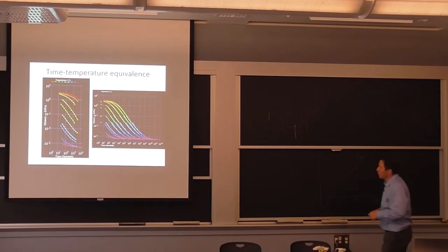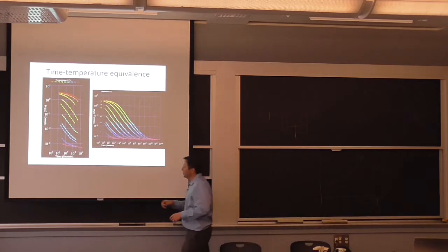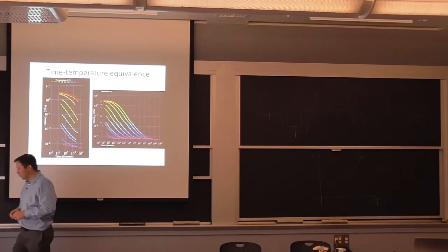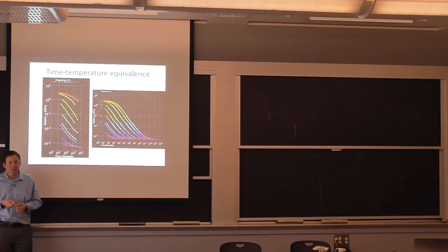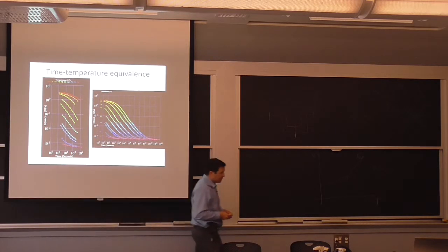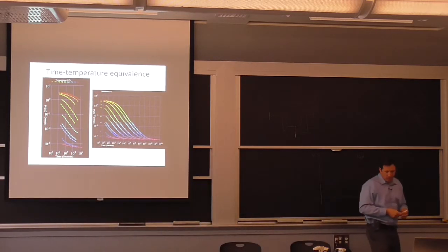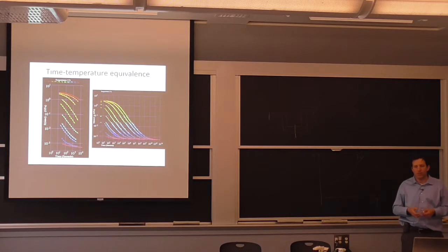So this superposition or equivalence doesn't allow you to predict the formation of crazes or the formation of shear bands or microvoids, because these become very localized processes and they're not just part of an overall bulk deformation behavior. So it's used, but it has a lot of limitations, and that's why ultimately you have to run, as I said last Wednesday, a typical test will last about 3 months. If you want to know if your plastic pipe's going to last for 25 years.